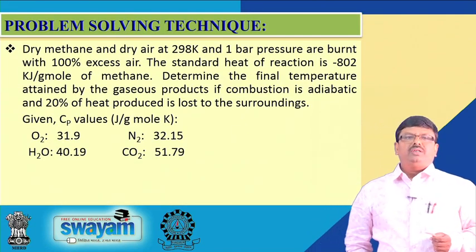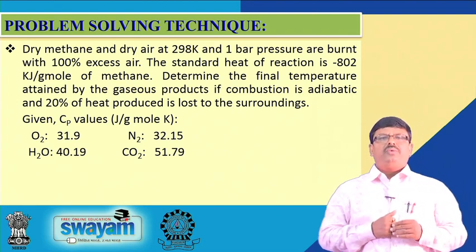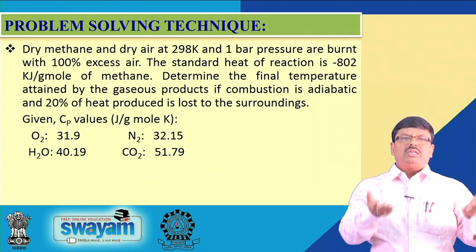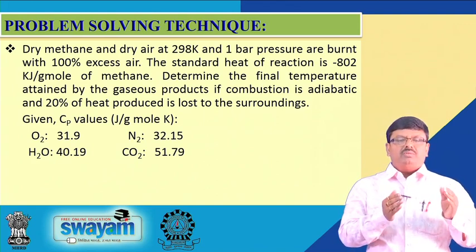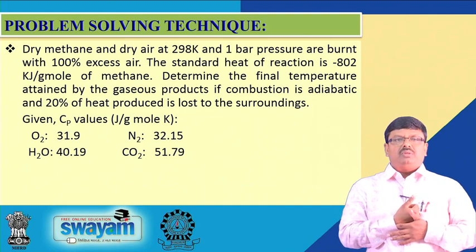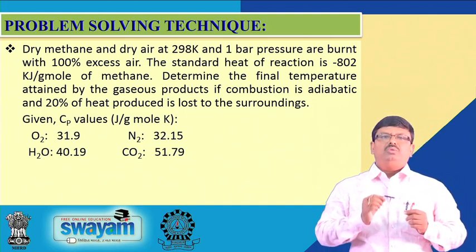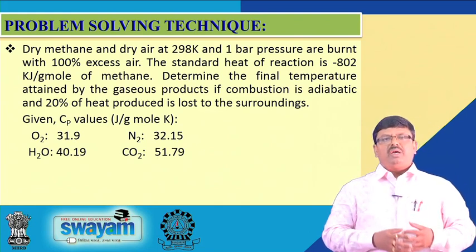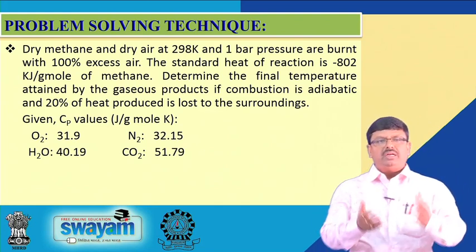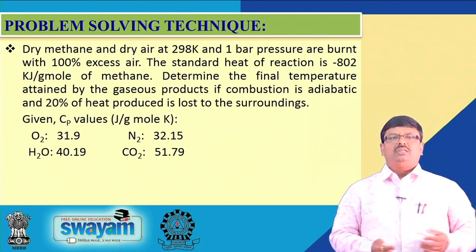Problem solving technique. Here is one more problem, which is a little bit different in nature. Dry methane, considered as one of the combustible gases, has been supplied to the adiabatic combustion chamber, and 100% excess air has been supplied to ensure the complete combustion of this methane, where the heat of reaction is minus 802 kilojoule per gram mole of methane. So, that is the standard heat of reaction.